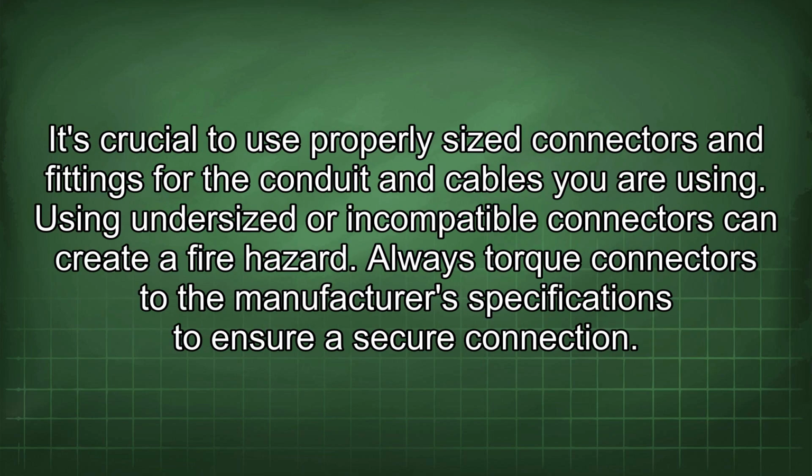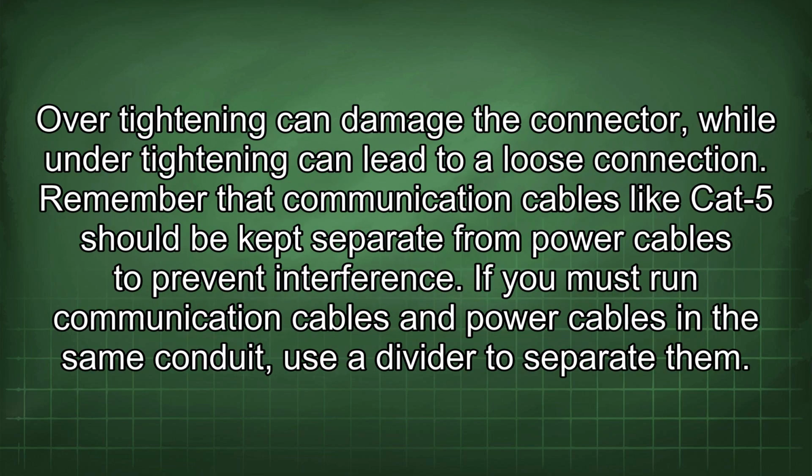It's crucial to use properly sized connectors and fittings for the conduit and cables you are using. Using undersized or incompatible connectors can create a fire hazard. Always torque connectors to the manufacturer's specifications to ensure a secure connection. Over-tightening can damage the connector, while under-tightening can lead to a loose connection.